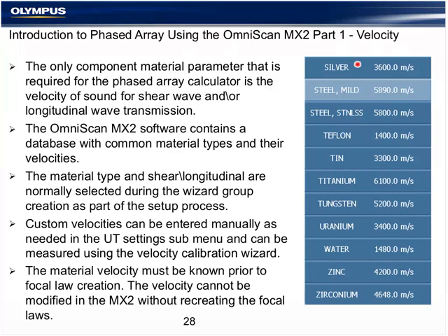Normally, for carbon steel weld inspection using normal P numbers and typical API piping, selection of the velocity from the database is just as accurate as your ability to measure it for the delta. There are several ways of measuring velocity. We'll talk about those in later sections. Normally, it's selected from the database.